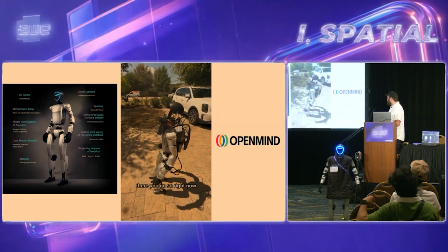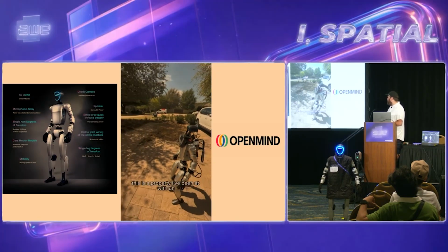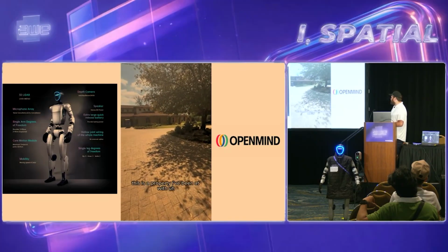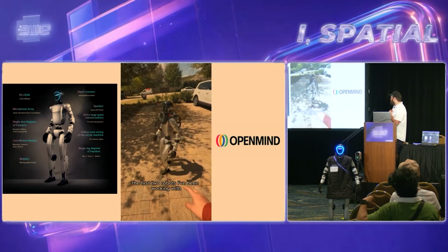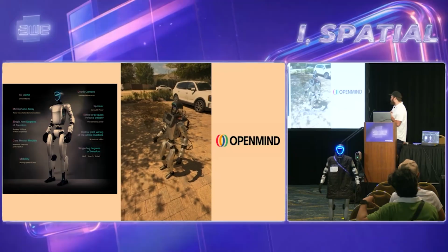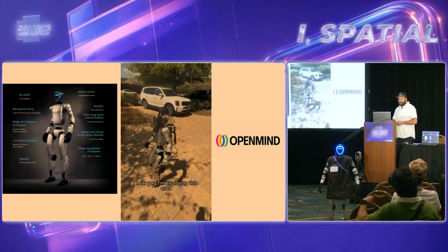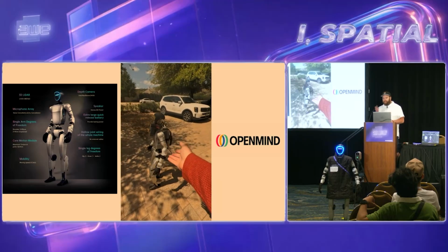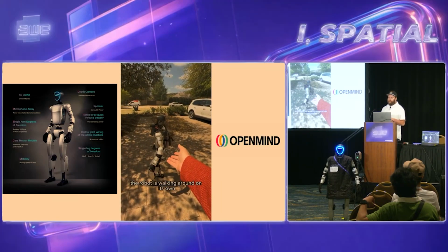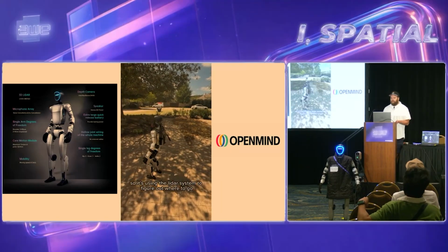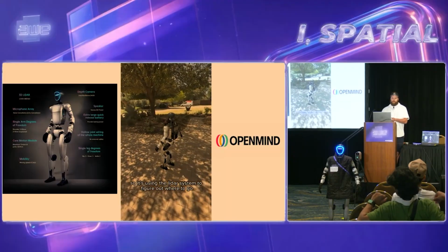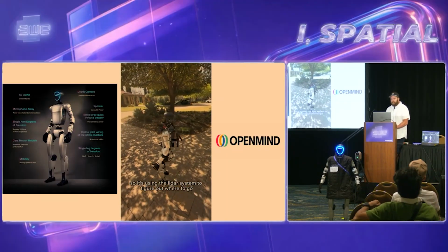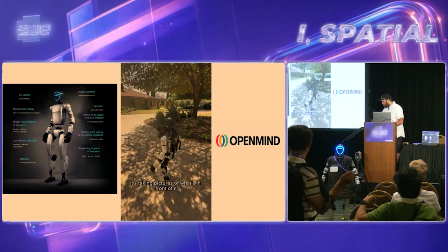There you go. So right now, this is the property I've been at with the first two robots I've been working with. On the G1, you've got a LiDAR and a depth camera, and a magnetometer, IMU, gyro, all the fun stuff that actually lets it sense the world. In the same way that a Waymo figures out where to go, this will actually figure out what obstacles are near it and then path plan.